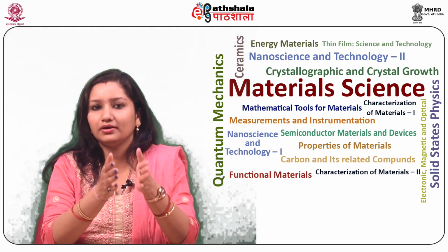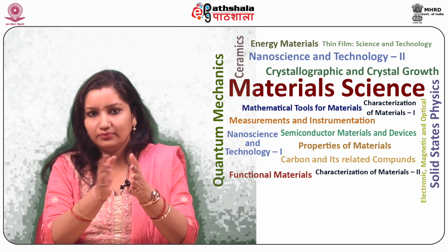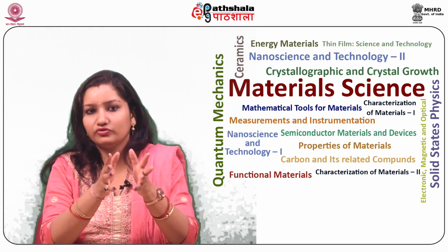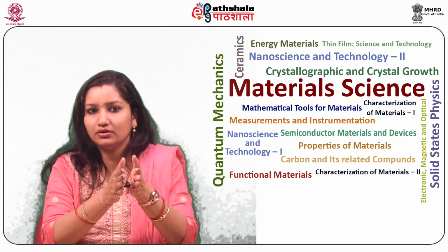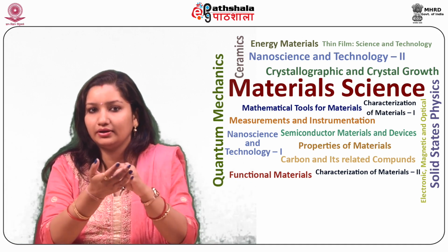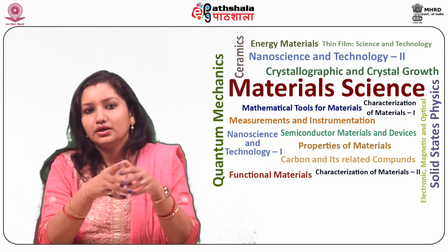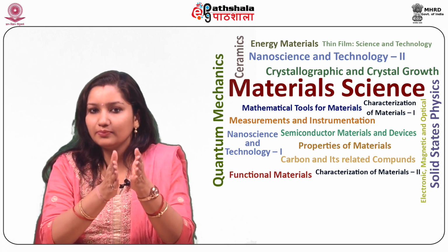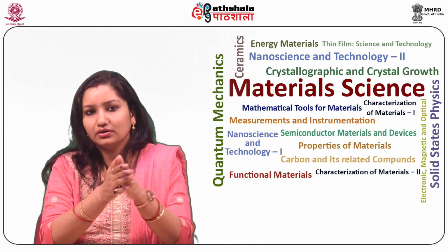Another example is the metal semiconductor, Schottky type contact solar cell. Then the next is the most convenient and the most conventional, which is a p-type semiconductor joined with an n-type semiconductor. When the same semiconductor is made p-type and n-type, that is a homojunction based solar cell. Then another one is p-type semiconductor 1 and n-type semiconductor 2, which will be a heterojunction based solar cell.